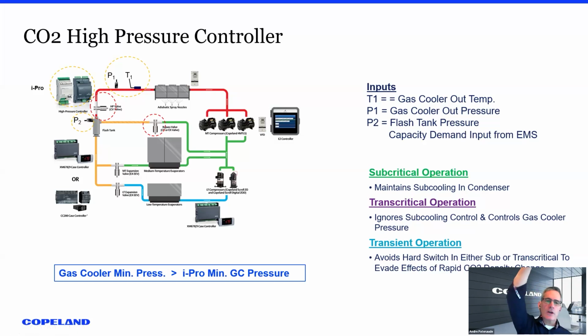You don't want it 20 feet below, where you've got head coming down and a couple of extra pounds of pressure higher than it thinks it really is at the outlet of the gas cooler. Because P1 and T1 are the sensors that are measuring subcooling set points and adjusting a valve. So you want to make sure that your pressure and temperature are as close to saturation as possible so you can drive the valve effectively.